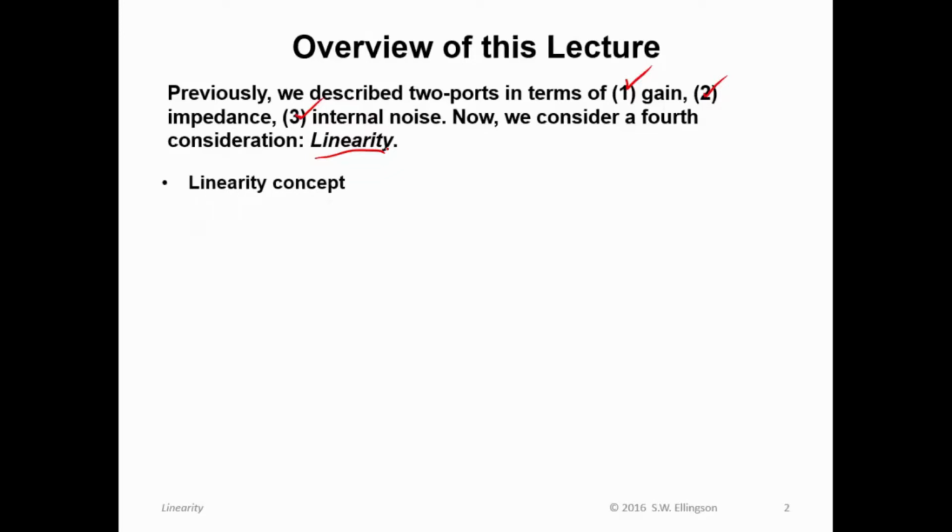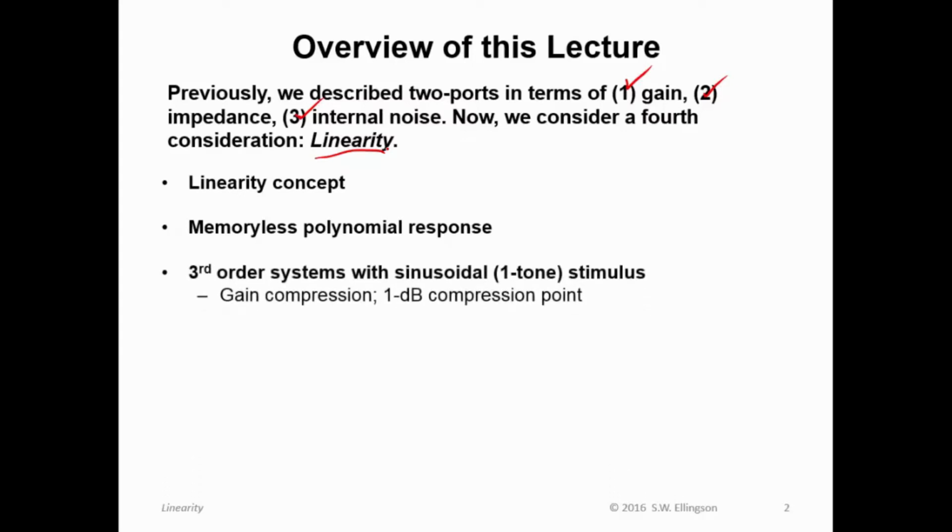First, we'll describe the linearity concept, which you hopefully already have some familiarity with, but will put you on firm footing. I'll discuss the specific concept of memoryless polynomial response, which is a particular way to characterize linearity of two ports. I'll talk about third-order systems with sinusoidal, that is single-tone stimulus. So these are systems in which we apply this model in a case where we have a single RF tone applied to the input. And that will result in two concepts.